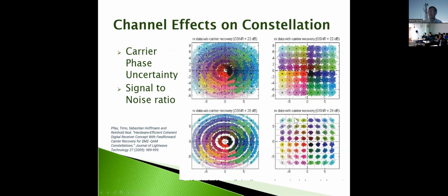Well, here now for each symbol we're sending, what did I say, 8 bits or 6 bits, 6 bits, right? 2 to the 6th is 64, I think. So we're able to send 6 bits, but when you do this, your noise margin here is terrible, right? We see that with this, we need a signal to noise ratio on the order of 22 dB.